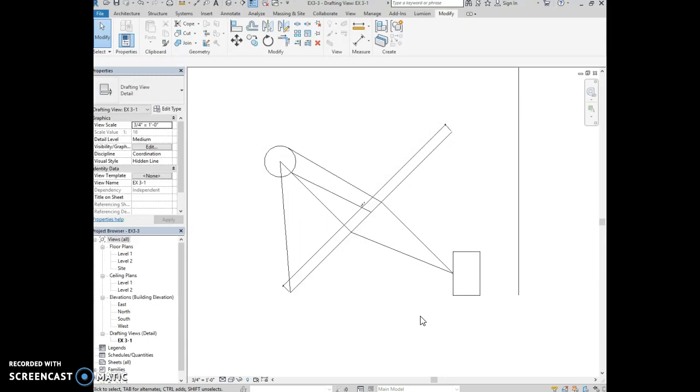Your book has some more examples of using the window tool and selecting multiple elements, so I encourage you to look through that. Let's go back to the Copy tool. The Copy tool allows you to accurately duplicate elements. You will select the items you want to copy and then pick 2 points that represent an imaginary vector which provides both length and angle, defining the path used to copy the object. You can also type in the length if there are no convenient points to pick in the drawing. We're going to try both next.